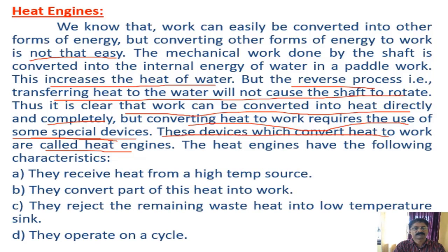They receive heat from the high temperature source. They convert part of this heat into work. They reject the remaining waste heat into a lower temperature reservoir or sink. Also they operate in a cycle. These are the very important characteristics of a heat engine. It should have a high temperature source or reservoir from where it absorbs heat, and it converts only part of that heat into work, and the remaining heat is rejected into the low temperature sink, and also the entire heat engine device operates on a cycle, okay.